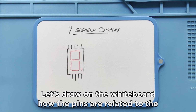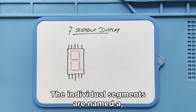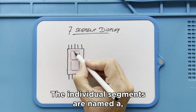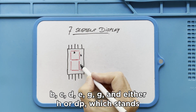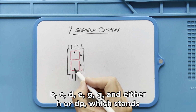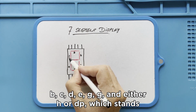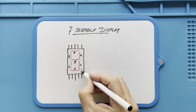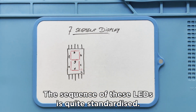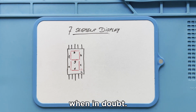Let's draw on the whiteboard how these pins are related to the LEDs on the display. The individual segments are named A, B, C, D, E, F, G, and either H or DP, which stands for decimal point. The sequence of these LEDs is quite standardized, but it is always safe to consult the datasheet when in doubt.